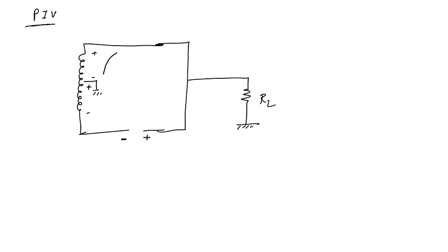When this diode is forward biased, a current will flow through the load resistance and we will obtain a voltage across this load resistance. Now during the positive half cycle, if the input is at its maximum, the current through the load resistance will be maximum. Also the voltage obtained across the load resistance will be maximum.